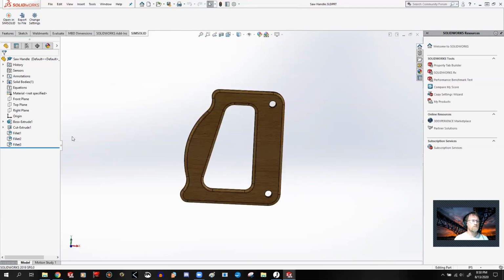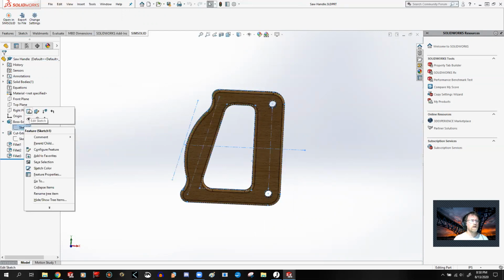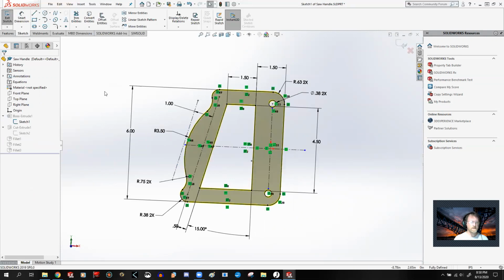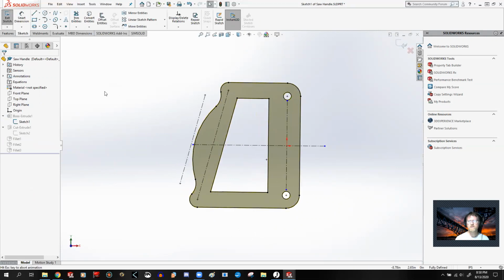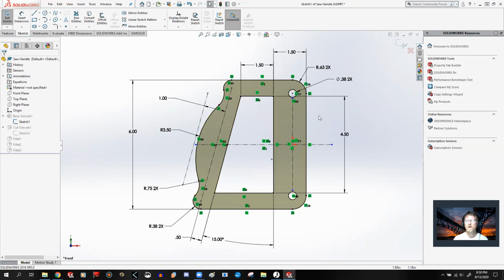This is, of course, fairly complex. So again, the first thing I'm going to be doing is opening up these sketches. So if you wanted to have them open to begin with, that'll help me out. And I'm going to edit sketch. Hit Control-8, and it shows that to me normal. And I'm going to be looking at the first off the shape.